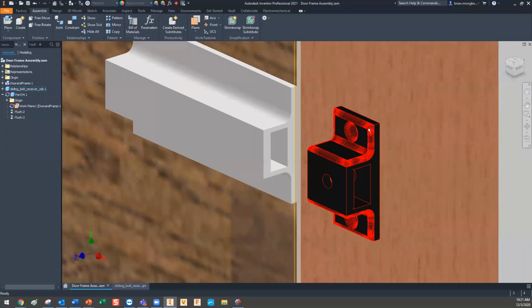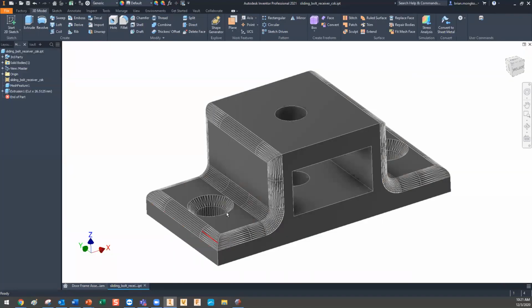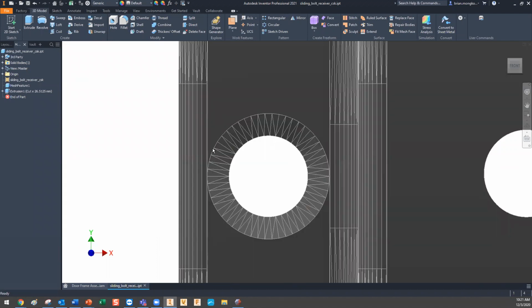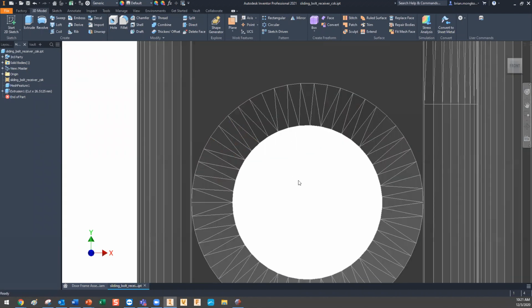The last part I wanted to show was messing with these tapered holes here. So if the customer wanted me to create a different specific tapered hole with specific values and they don't know what this is either, then I'll go ahead and show you how I can go about editing these. So we can use what is called direct edit modeling inside of Inventor. And there are some subtle tools here, direct and delete face, that allow you to do that, especially now that it's a 3D solid.